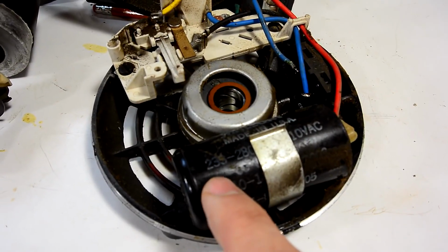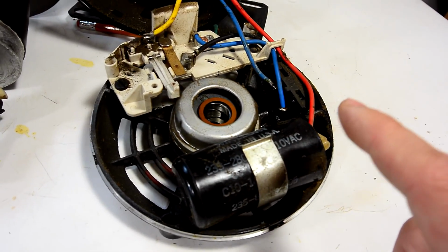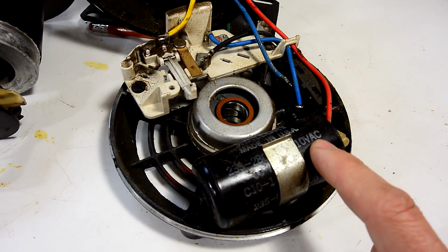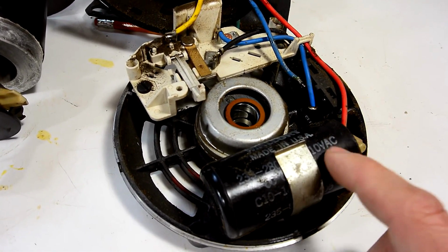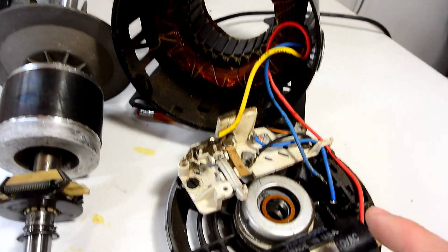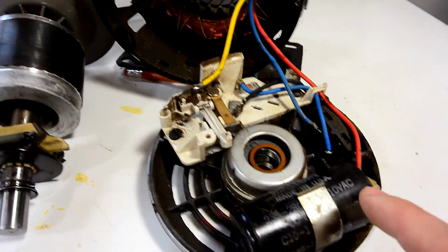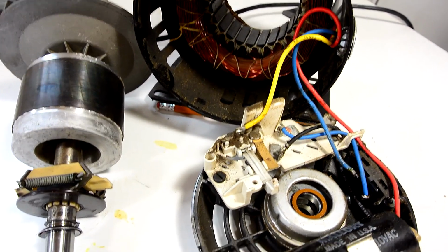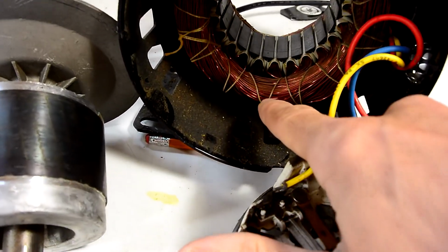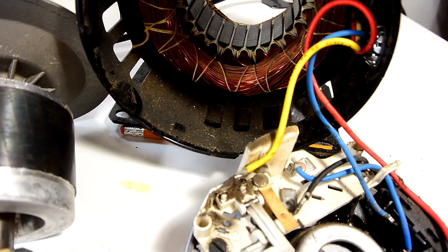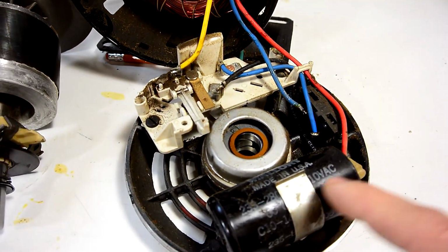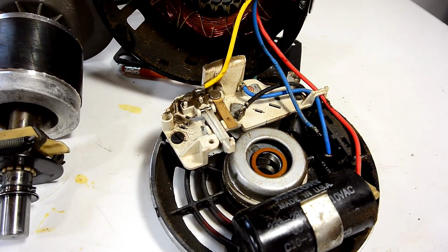Also, this capacitor is an electrolytic capacitor and is not designed to take a continuous AC load. If it got that kind of load, it would burn out, and to have a condenser for this size motor would be quite expensive. And because we turn off the winding once the motor's up to speed, we can also use a much thinner winding for the starter winding and save a bit of money that way, because copper is expensive. So just to turn off the starter winding makes an awful lot of sense.